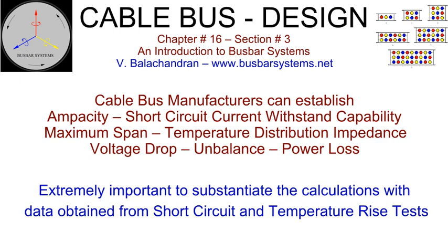As has been stated earlier, the prediction of current distribution, magnitude and phase angle, in each parallel path of the same phase, in the maze of a matrix with similar parallel paths of other phases, is very complex. Consequently, evaluating the equivalent resistance, inductance, and capacitance per phase is challenging. For the same reason, it is difficult to analyze the effect of short circuit forces and the distribution of temperature. The importance of conducting the short circuit test and temperature rise test for a given configuration cannot be overemphasized.